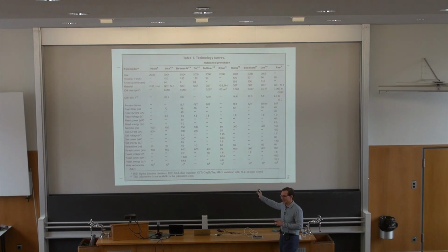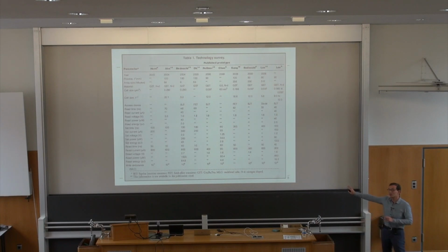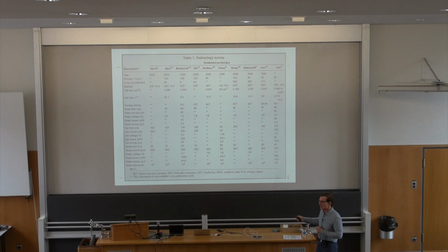It's going to be much more than 10 to the 4, right? It's actually a lot. So write endurance is a huge problem with these memories. By the way, this 10 to the 4 is not terrible. If you look at some of the flash memories that we have today, that's actually much lower than 10 to the 4. That's why we're going to cover flash memory later on.